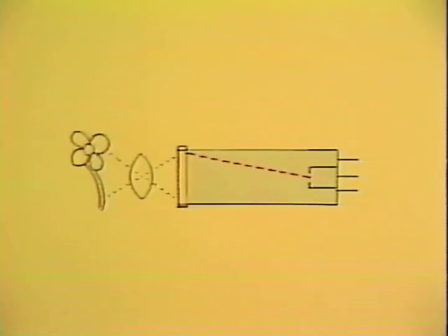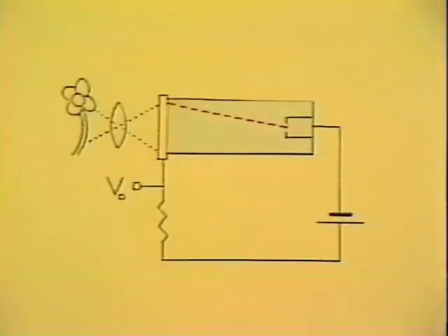Instead of using a movable photoelectric cell or a rotating wheel with lenses, the target is scanned by an electron beam. The other end of the vidicon tube contains an electron gun. This produces a beam of electrons which are formed into a fine beam and aimed at the target, just as in the picture tube. When the beam hits the target, it completes a simple electric circuit. If a bright light falls on the surface of the tube, the resistance of the target will be low. If a dim light or no light falls on the face, the target resistance is high.